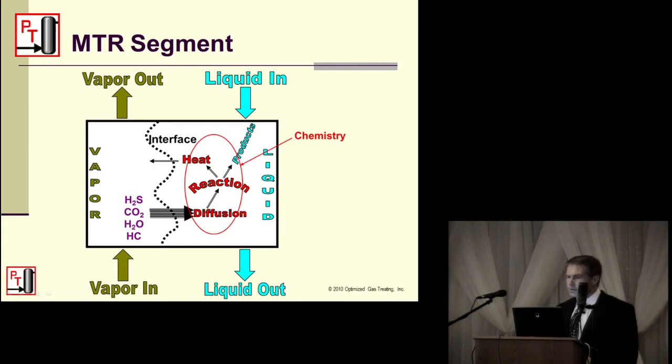The rate of mass transfer of each chemical species is what determines the separation on a tray or a packing segment. And so what differentiates and makes mass transfer a little bit harder than heat transfer is we're dealing with multiple entities transferring across this interface, not just heat, like in a shell and tube exchanger. We have equations we have to solve for everything that is transferring phase, but that's just more computations that are required. It really isn't anything that is horribly rocket science.